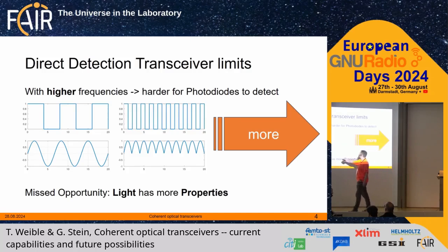Let me show what it is, because if we increase the frequency, like increasing the steps, and we want the photodiode to detect our signal, we have to change our threshold. Now you see here we have -1 and 1, so that is the threshold you could put to describe my 1 and my 0. Now I have to change it.